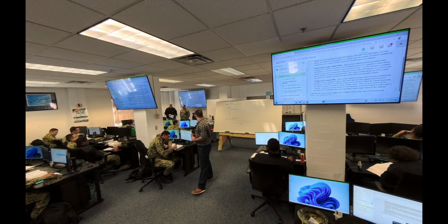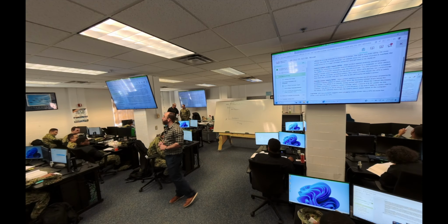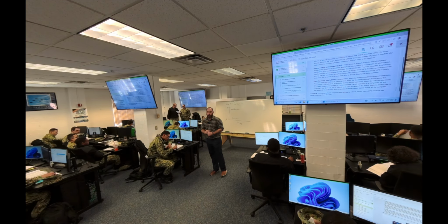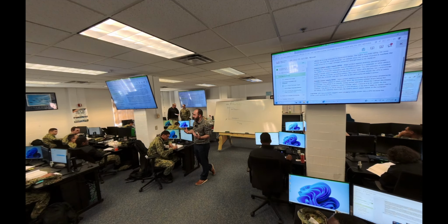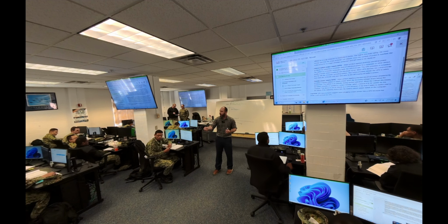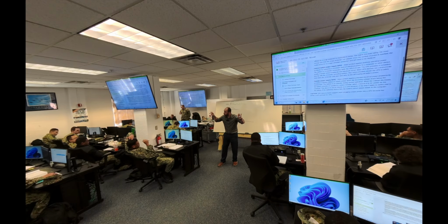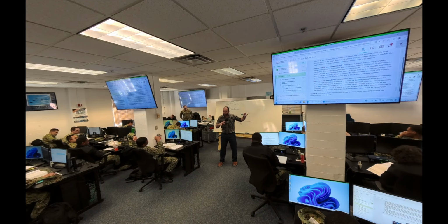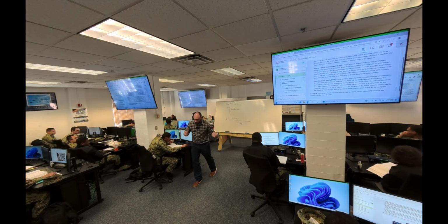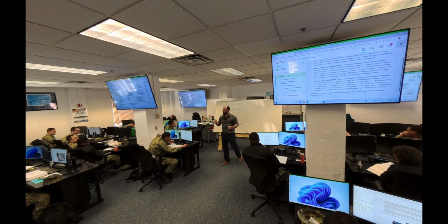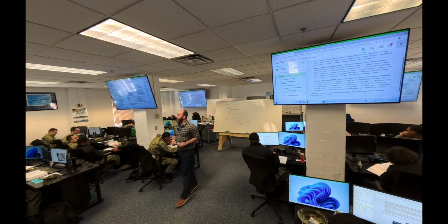Any questions on any of this? Now, you don't want to plug everything into a UPS. For example, a printer. When it heats up that corona wire that we'll learn about later, it takes a lot of electricity. If you turn on a vacuum, what do the lights in your apartment or house do? They kind of dim. Imagine if that was operating off a battery. It's going to cause a problem. That printer draws a lot, so a printer should never be plugged into a UPS.